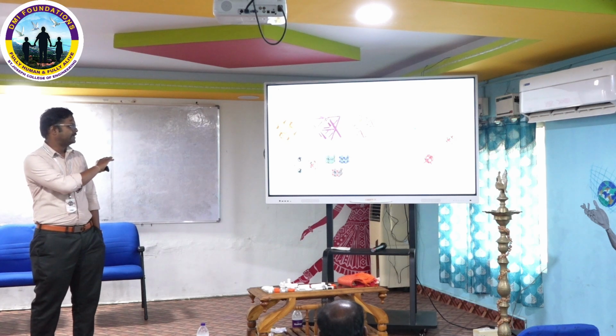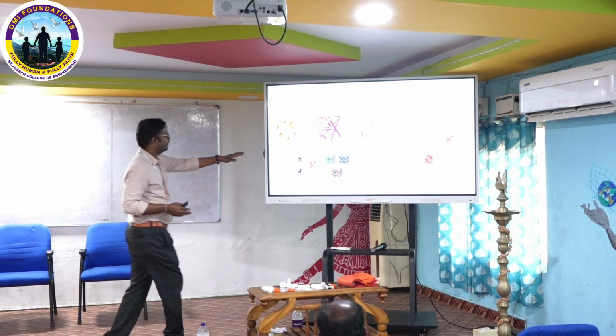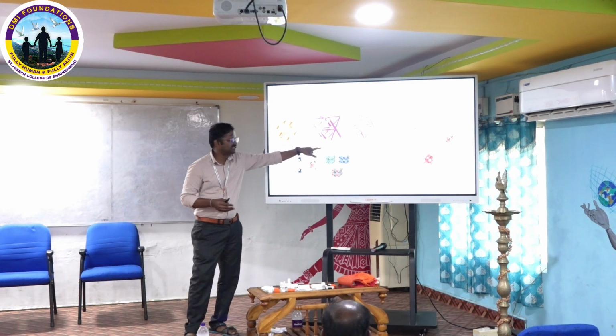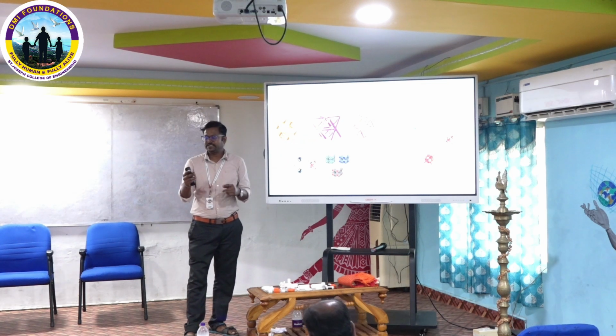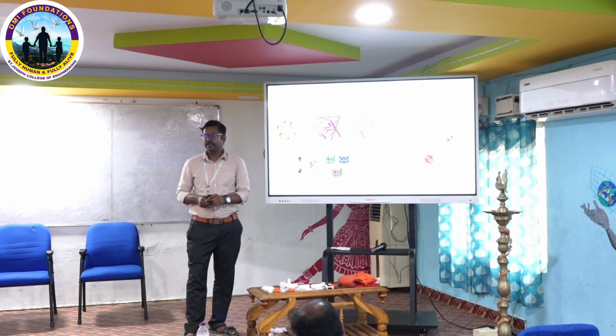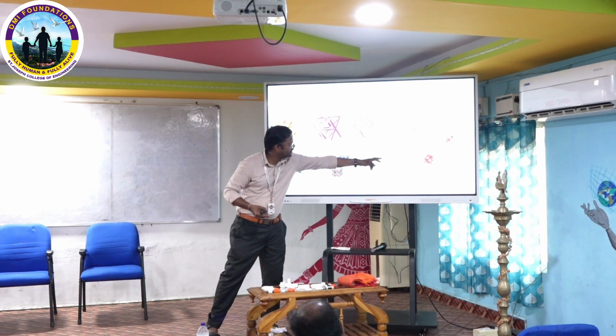This is interpenetrated lattices. It's nothing but we incorporate, for example here, bending dominated and stretch dominated lattices. What will happen? We can achieve both properties in a single unit. Okay? It will give more energy absorption also. It will give more stiffness also. So you can see the graph here.